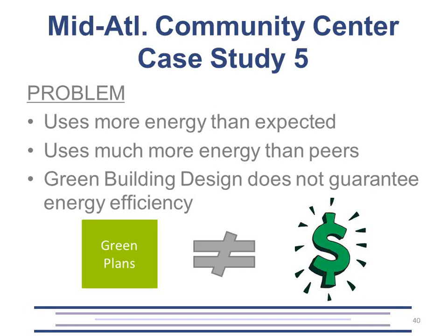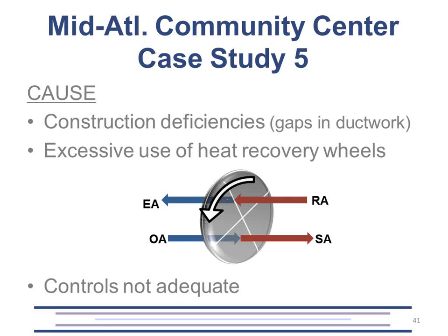Many deficiencies were then identified. Substantial gaps in the ductwork throughout the building were found, leading to short cycling of the air-conditioned air. Most of the costly supply air being produced was never making it to the occupied spaces. Also, the heat recovery wheels, a great addition for highly energy efficient systems, were controlled so poorly that they were actually contributing to additional energy waste. This great technology has many advantages, but if the controls are not implemented precisely and the system isn't installed correctly, then it certainly can impact the energy usage negatively.